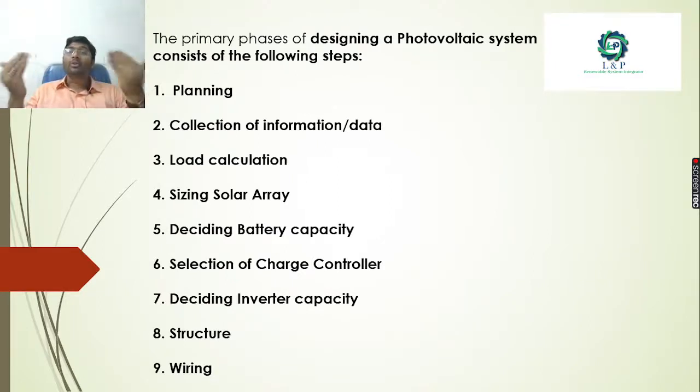Sometimes in certain locations we will have a big space but the load will be very small, so we can put solar panels over the entire area. In other locations, at the rooftop, they will have a big load but very little area to put the solar panels. For that we need to look at separate locations to provide the solar array sizing. So a site visit is very much important, and collecting the information and data is very much important.